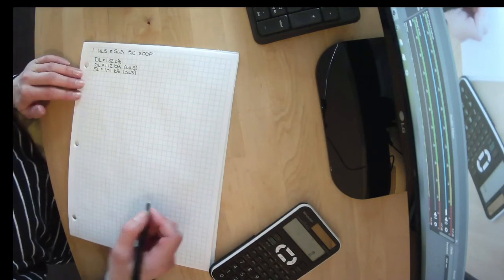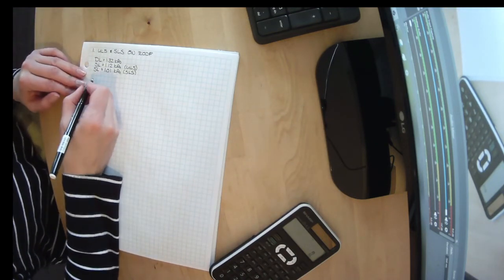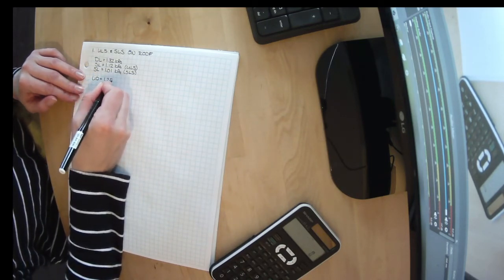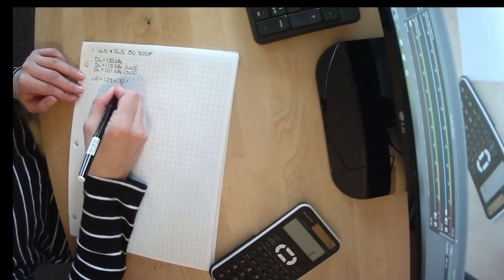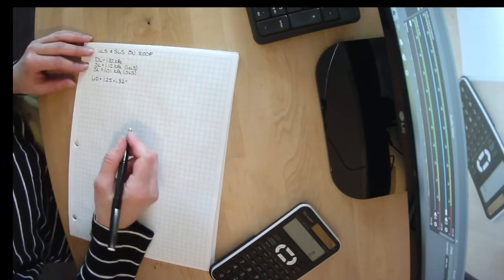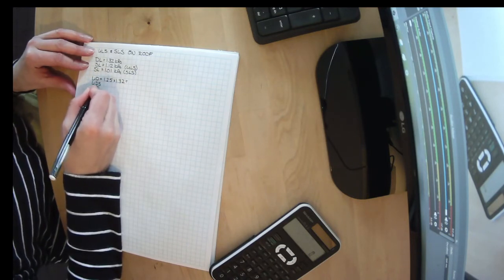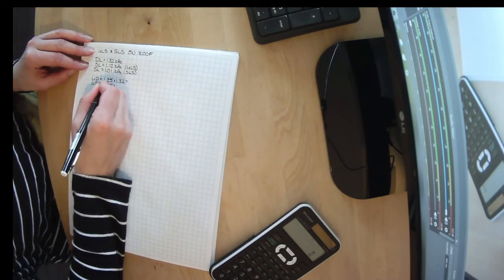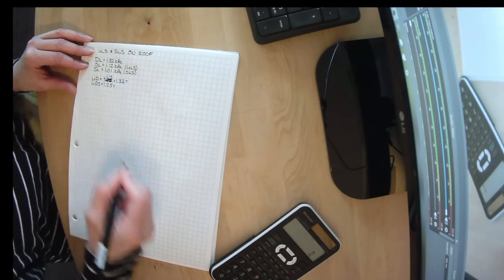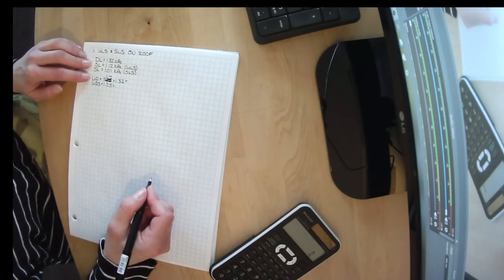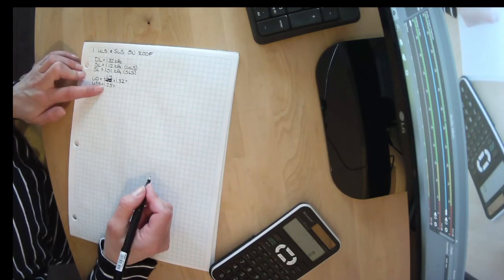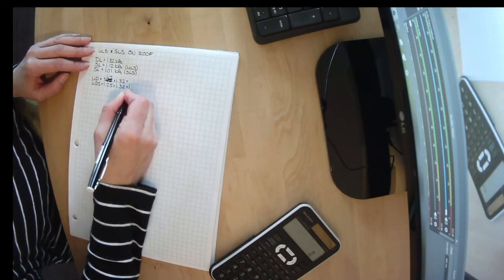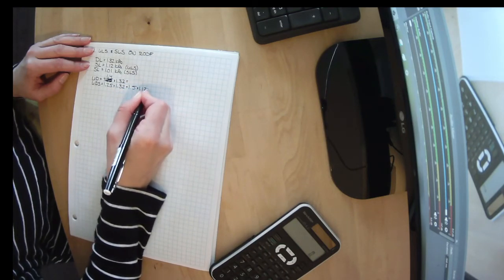And we want to know our different load combinations for our roof. Well, we could have dead all by itself, or 1.25 times 1.32 kPa. I'm going to write them all out and then pick up my calculator. Or we could have dead and snow, or 1.25, 1.4. You guys were all yelling it at me, right? 1.4 times 1.32 for our dead all by itself. And for dead and snow, 1.25 times 1.32 plus 1.5 times 1.12.